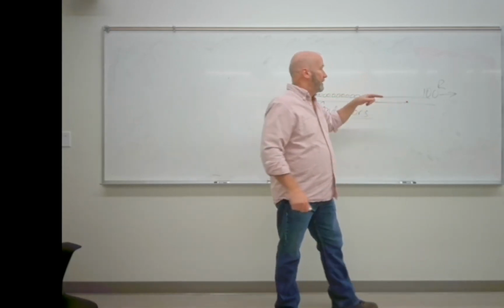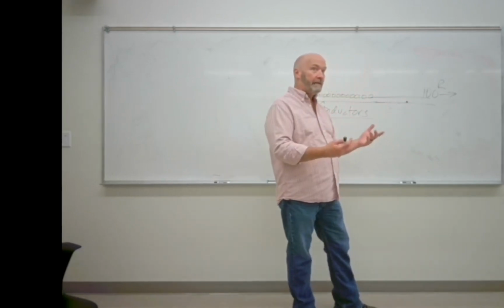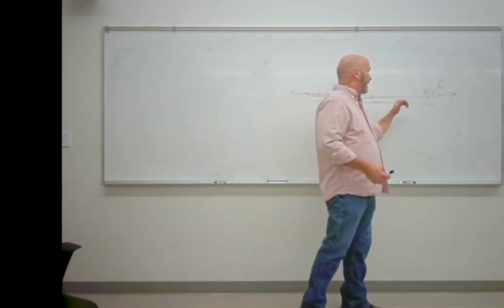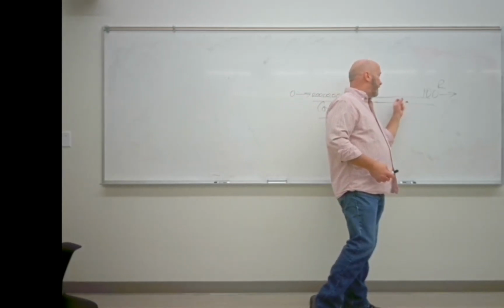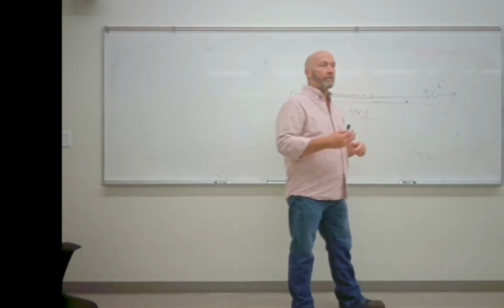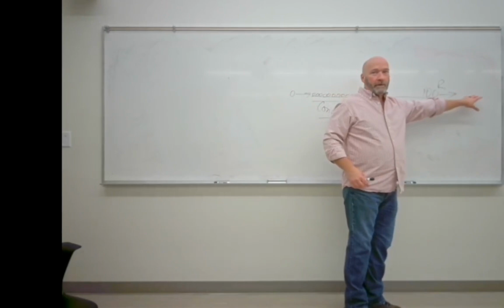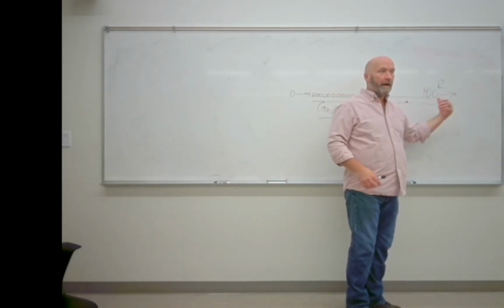So you drive a nail into that wire and it breaks through the insulation, and we'll talk about that here in a second. Now you've got a path for the electricity to flow through the wire, and now you've got what we refer to as a short circuit. Suddenly, whatever's down there doesn't work anymore because you shorted it out.